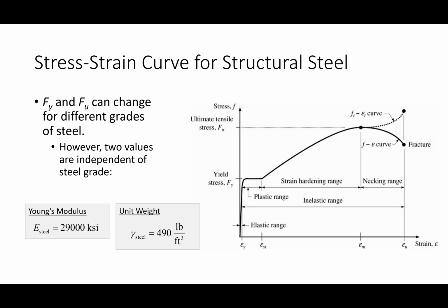Now, we can characterize this behavior with really two properties. The first is, when does elastic behavior stop? For all intents and purposes, we'll say that elastic behavior stops whenever the material starts to yield. Yielding is when those material deformations start to become permanent. To keep it very simple, it's when the material stops behaving like a rubber band and starts behaving a little bit like taffy: you yank it and let it go, and it has a permanent elongation. That happens at around the yield stress, okay?